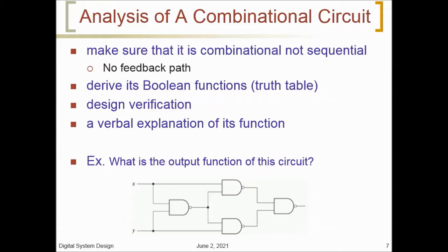The diagram of a combinational circuit has logic gates with no feedback paths or memory elements. A feedback path is a connection from the output of one gate to the input of a second gate that forms part of the input to the first gate. A circuit with a feedback path is defined as a sequential circuit and must be analyzed according to different procedures.